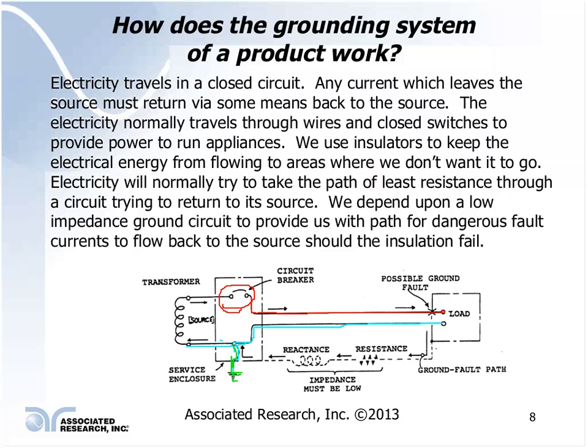So this ground circuit, in my product or in my house wiring, and within the product itself, in both cases, must be capable of handling this overload for this given period of time and not act like a fuse.